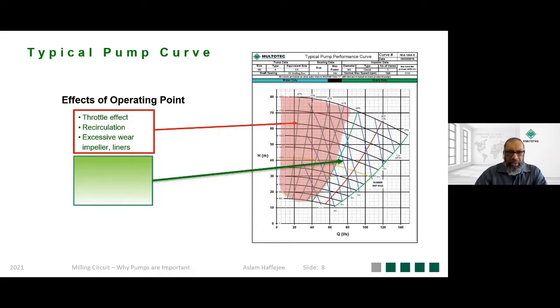Right, now we're going to look at the optimum position you should be operating on the curves. It's close to best efficiency. Generally, the tendency is to work to the left of best efficiency. People, I think, allow for a bit of expansion or increased flow rate, and that is the reason for doing this. You'll find here, like I said, you left up here best efficiency. This is where you tend to get your best efficiency out of your pump, to operate where it's supposed to.